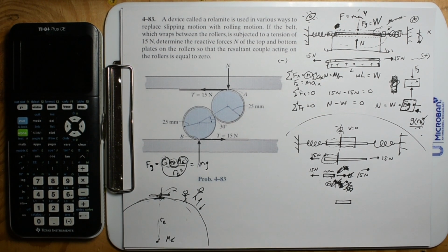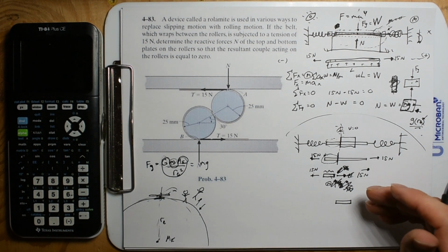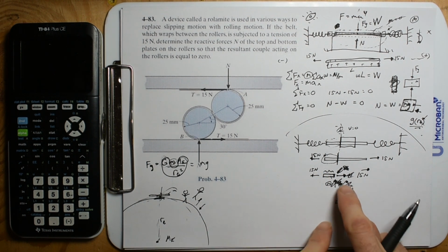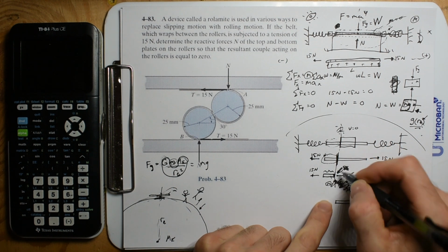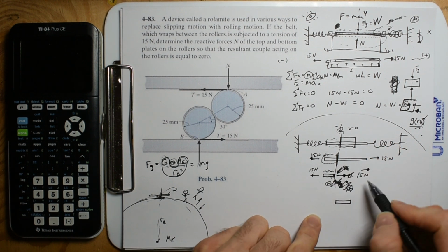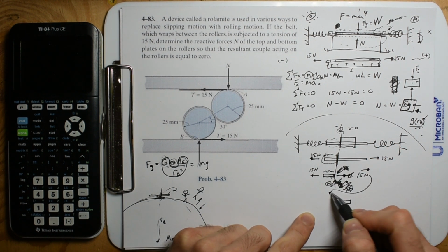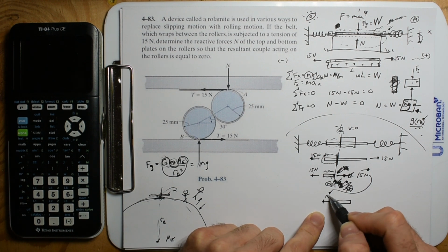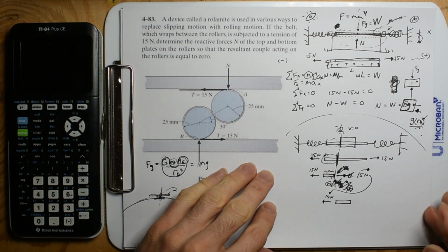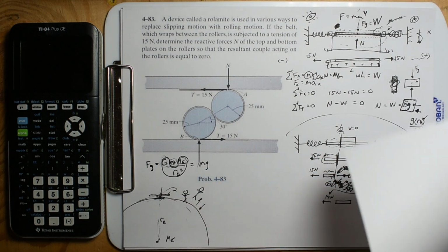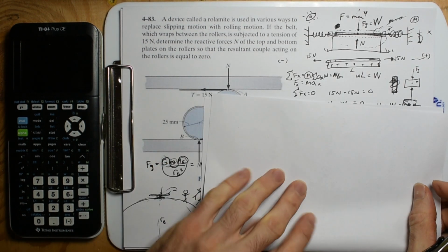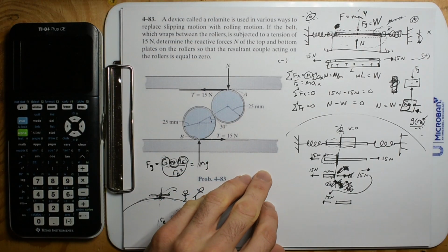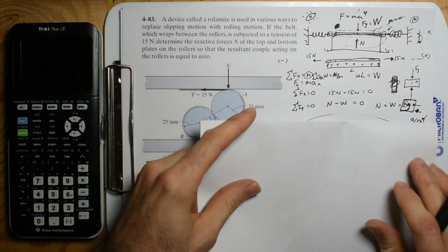Alright, hell yeah. This is going to be really good, because I swear, if I chop this out and I know the reaction right at this slice is 15 Newtons that way, I think it's not intuitive just to say that there must be an equal and opposite 15 Newtons this way. So let's slow this process down. And what I'm going to do is redraw this thing.